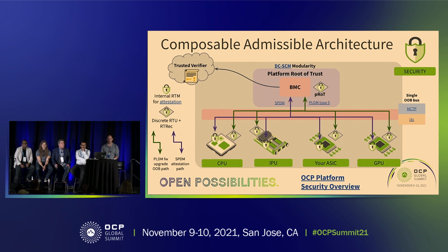That's right. Okay, thanks. One more thing there is that the amount of protection you have to provide between the device and the RTU is specific to your implementation. You may decide, for example, I'm really concerned about having interposers in my architecture, in which case you have to create a secure channel between the two. Obviously, that requires a more expensive device and a more advanced RTU. Or you can say, no, I'm designing my platforms in such a way that putting a physical interposer there is low risk, and in that case you don't have a special channel. But there has to be a secure communication, based on your requirements, between that RTU and the device that is getting the updates. I think we'll take the last question.